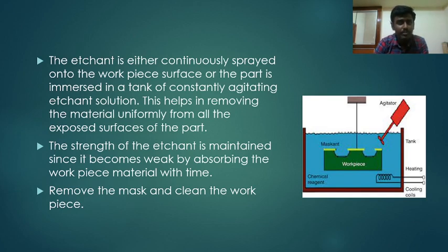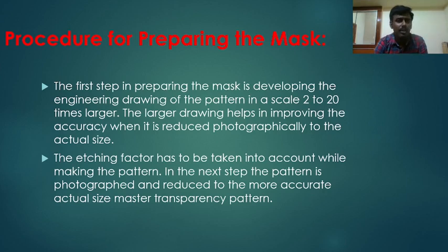And sometimes, where we need to uniformly cut 10 mm from all sides, somewhere the alkaline or acidic solution is more reactive, and somewhere it is not as reactive. So the depth of cut may vary from side to side. So to remove the workpiece material in a constant way, the solution needs to be stirred so that the material can be removed from all directions in an even manner. So, yes, that is all the working procedure we need to know.